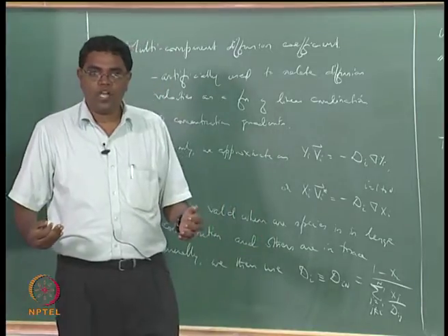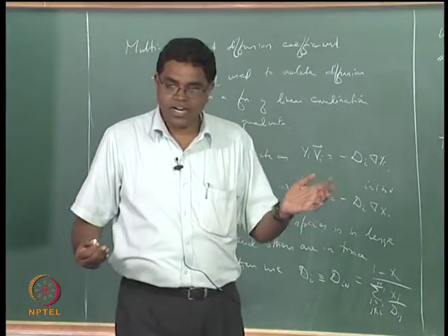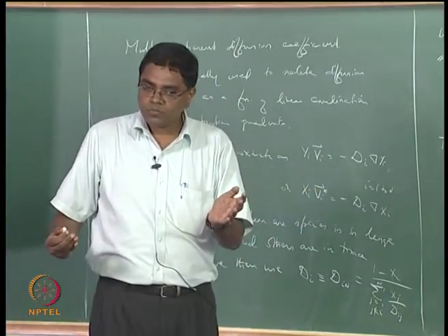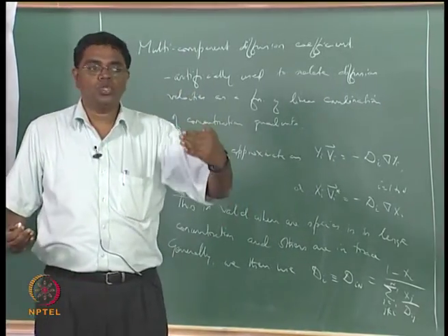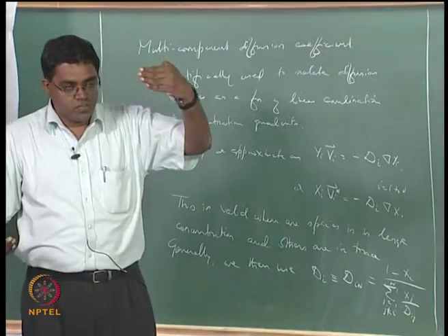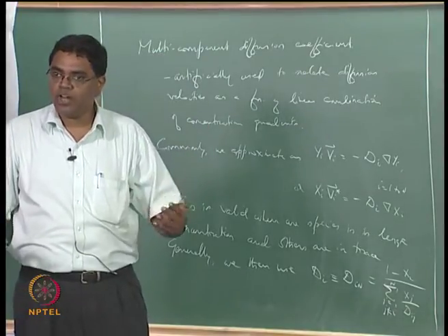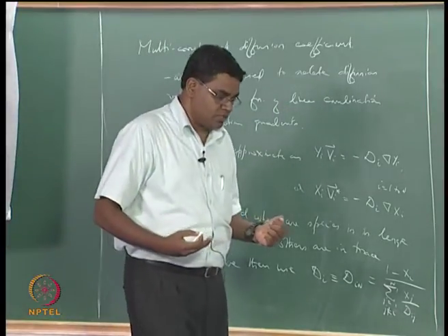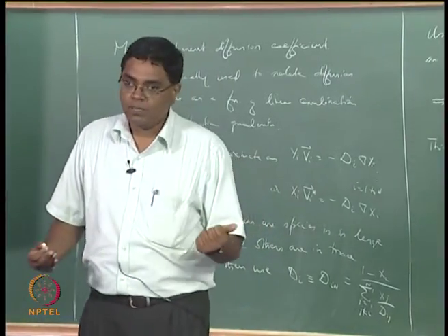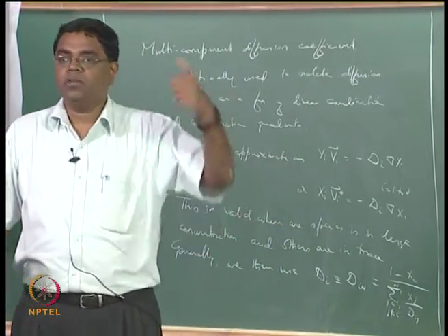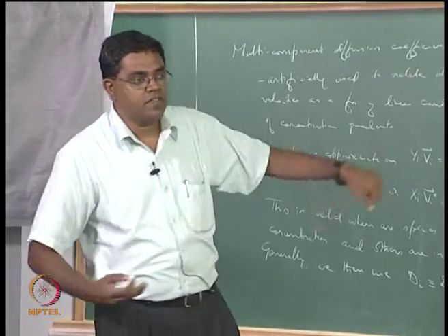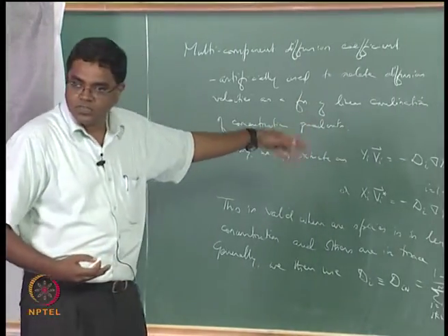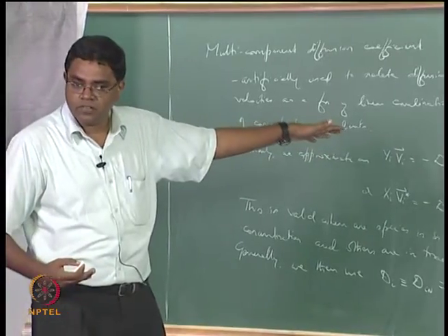And then we have the mass fraction Yi as an unknown for i equals 1 to n, for which we have n species conservation equations, in which Vi shows up, for which we have the multi-component diffusion equation, or its simplifications or many derivatives, which ultimately lead to something like Fick's law.